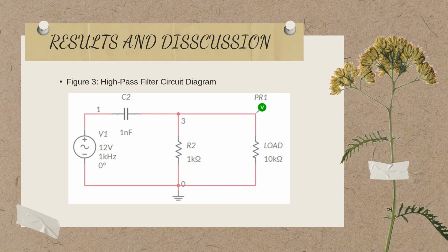The capacitor impedance increases with the decreasing of frequency. The high impedance in series tends to block low-frequency signals from getting to the load.